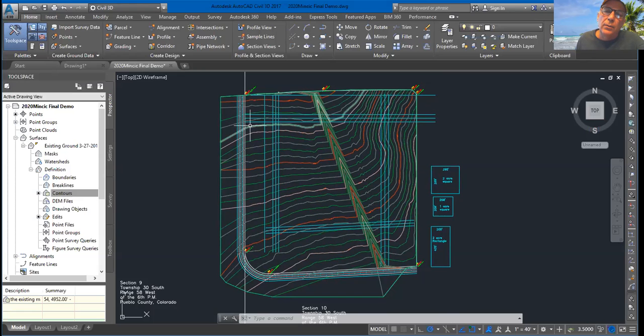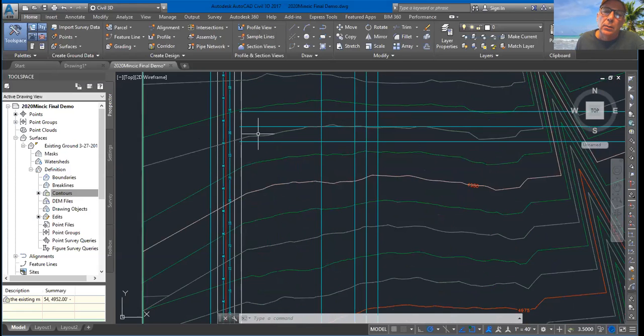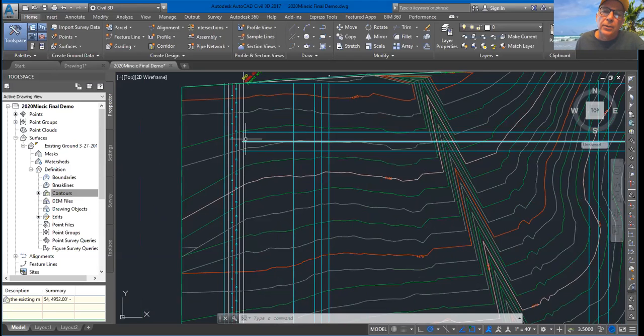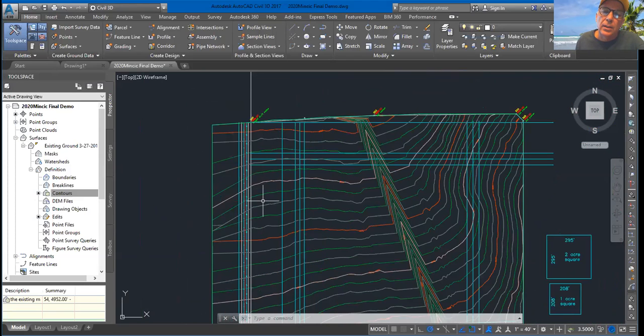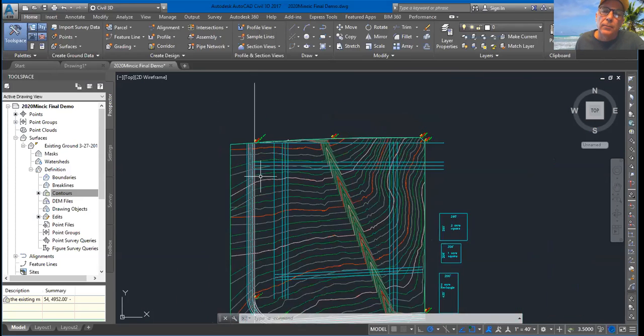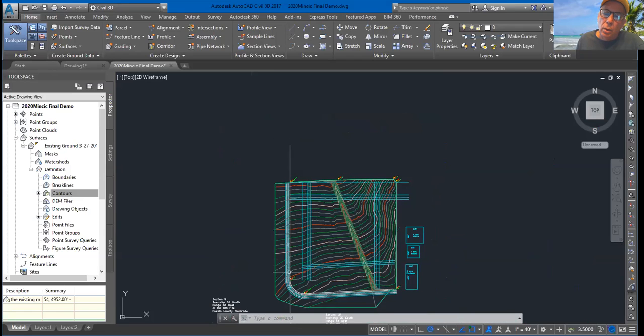Now, one of the considerations I would want to pull to your attention is that this major roadway does have some requirements as per the municipal government. Those are that you can only ingress and egress, or access onto this property, in one particular location, and it has to be defined. Well, in our situation, we need one for ingress, which is one to come in, and one to go out. So in this situation, I only touch this existing roadway in 2 places, one up here and one down here, or that's where I'm proposing to do that.